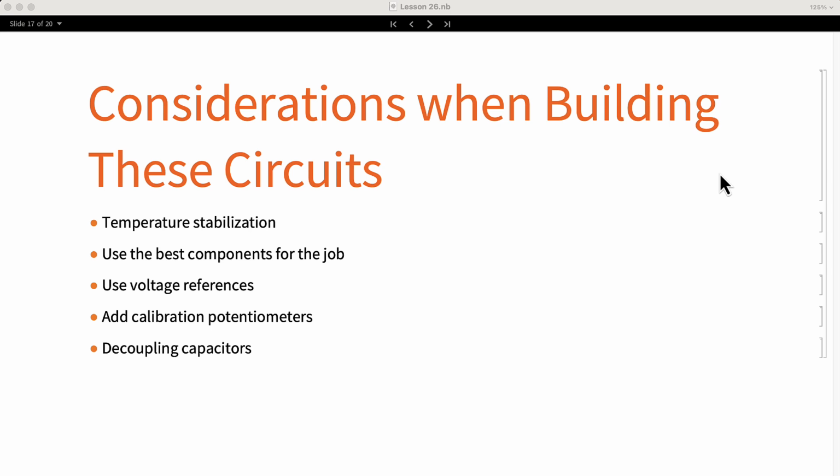In these modules, I use as reference the power supply voltage. My power supply is very good and it provides a stable plus-minus 12 volts, but it would be better to use a voltage reference to generate the constant voltage needed.